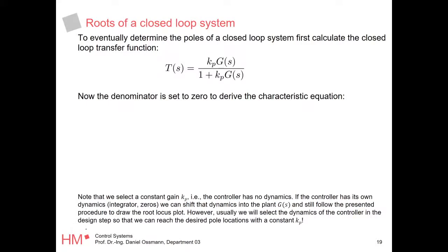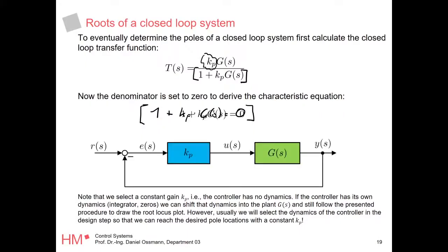Okay, so first thing we always need to do is think about what the root locus is telling us. Well, the root locus tells us something about the pole locations in a closed loop for only proportional feedback, right? So, how do we get the closed loop poles? That's actually pretty easy because we only need to set the numerator to 0, right? This should not come as any surprise at this point. So this guy here gives you the closed loop poles.